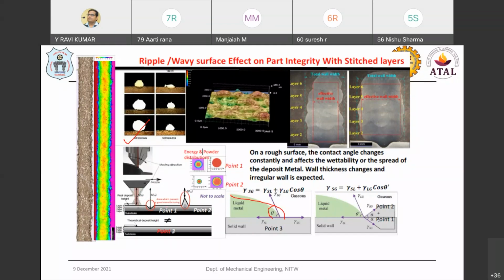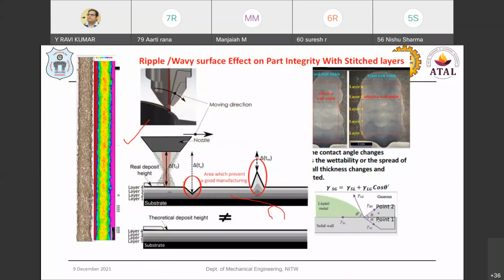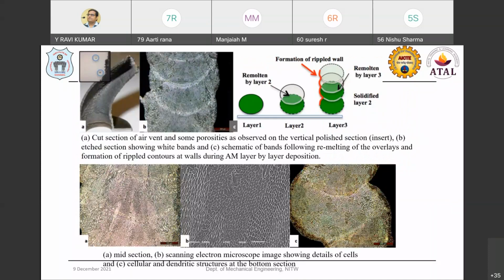If you have these kinds of defects, they automatically affect the part being manufactured, because where you have a hill area or a valley area, the focal length is going to vary. There, successive good part manufacturing is not at all possible. That is where we have the failures. That is why online monitoring systems are required to address such issues in the DED manufacturing process.